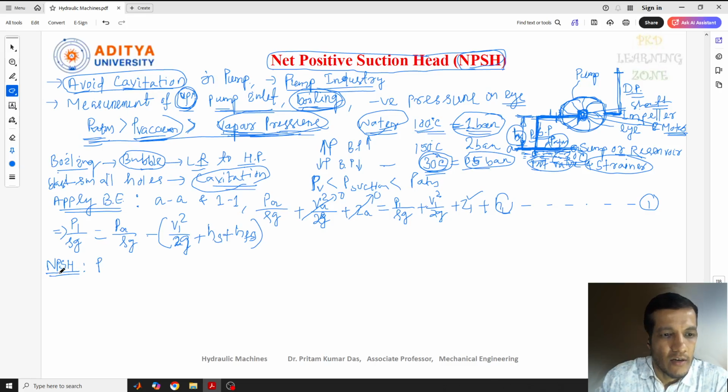That is called NPSH. So what is the absolute pressure head here? Absolute pressure head is nothing but P1 by rho g. And what is our vapor pressure head, which is supposed to be minus? That is PV by rho g. When you talk about the head, we need to consider rho g in the denominator.